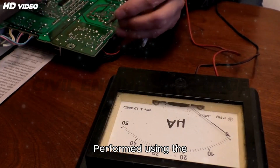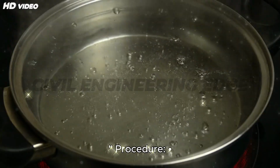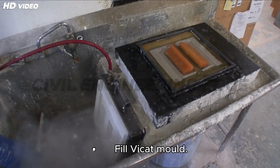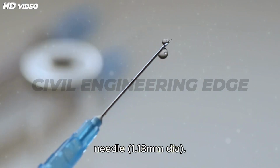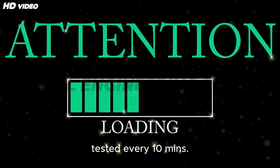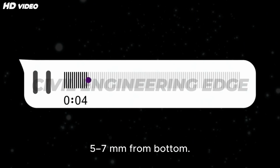Performed using the Vicat apparatus, IS 4031 Part 5. Procedure: prepare paste with standard water P%. Fill the Vicat mold. For initial setting, use a needle 1.13 mm in diameter. Penetration is tested every 10 minutes.